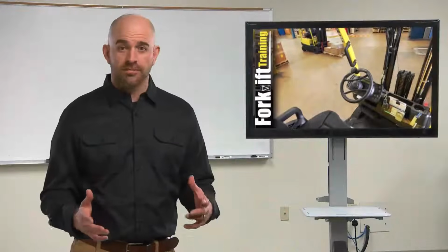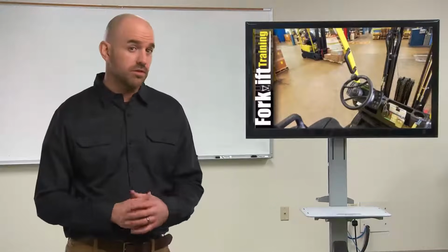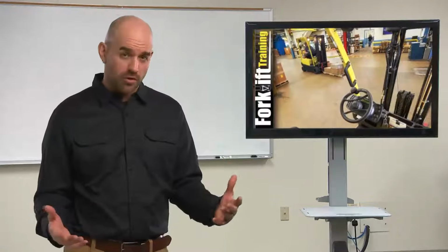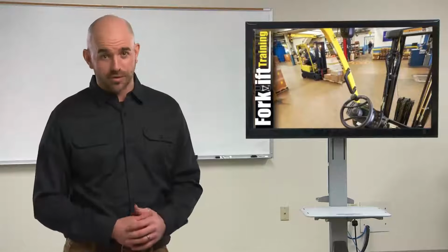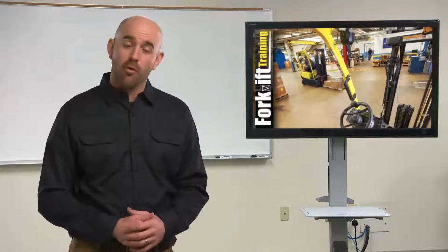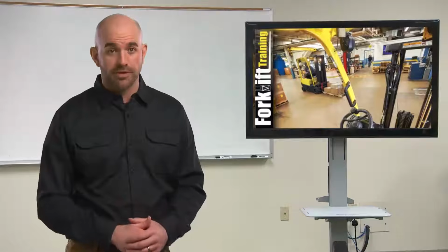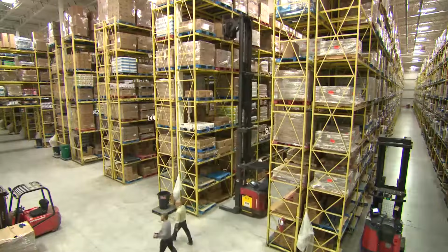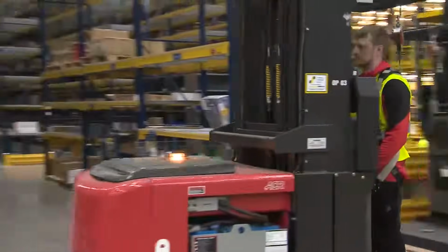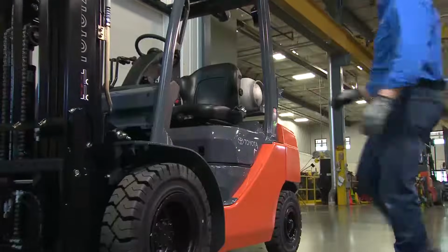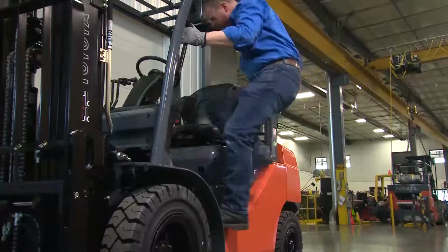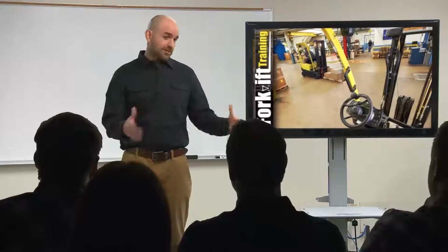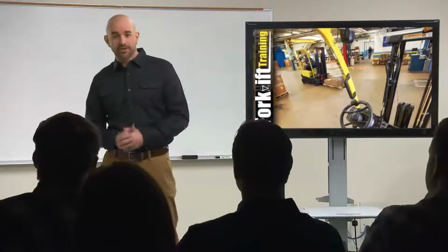In a typical workday, you may use a forklift to move dozens of loads of all shapes and sizes throughout your facility. Although this task can seem boring and routine, especially if you're an experienced operator, it's crucial not to overlook the potential dangers that a forklift can pose. Forklifts are surprisingly easy to tip, especially when handling a load. Now take care and remember these three basics. Wear any required personal protective equipment, or PPE, mount and dismount using 3 points of contact, and fasten your seatbelt right away. Come on, let's get out there and actually see what's going on.